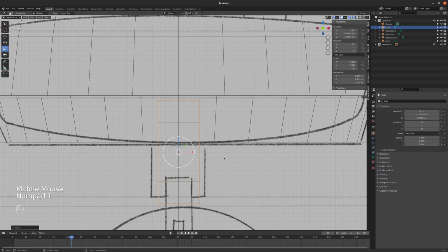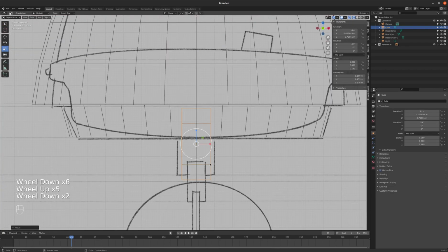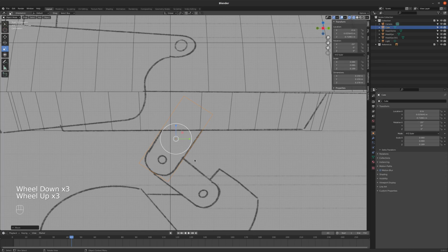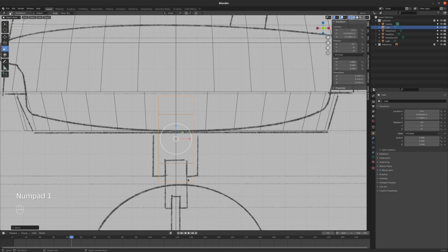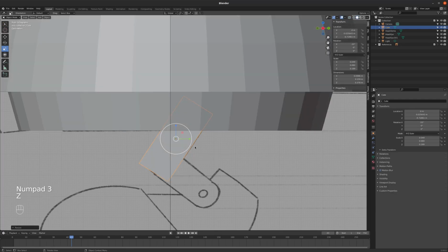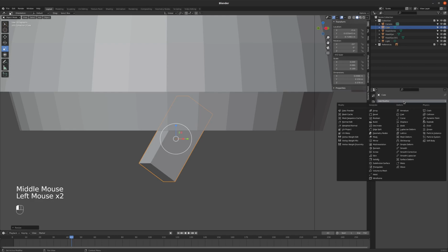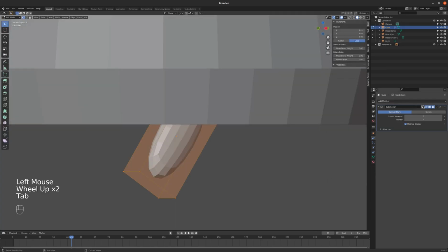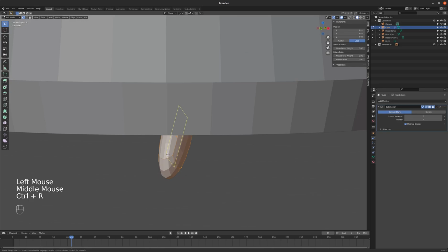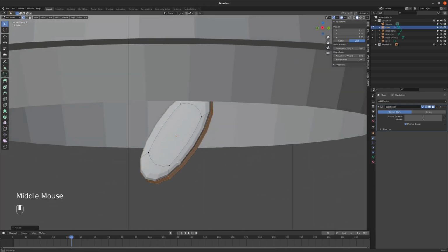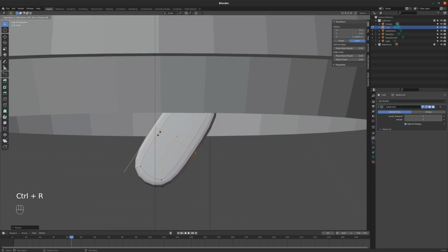Okay. And I think I'm actually going to swap the thickness of these two pieces. So I've got the upper leg piece outside of the shin piece, and I think I'm going to put it inside. So it's going to be the length of the shin piece, and then I think that'll make more sense. So there's my upper leg piece, and we're going to give this some curvature just really quickly with a subdivision surface modifier. Give it a couple of subdivision steps and then tab into edit mode, conform our edit cage to our modifier, and scale in X. We'll do some loop cuts here. Okay, do a loop cut here.